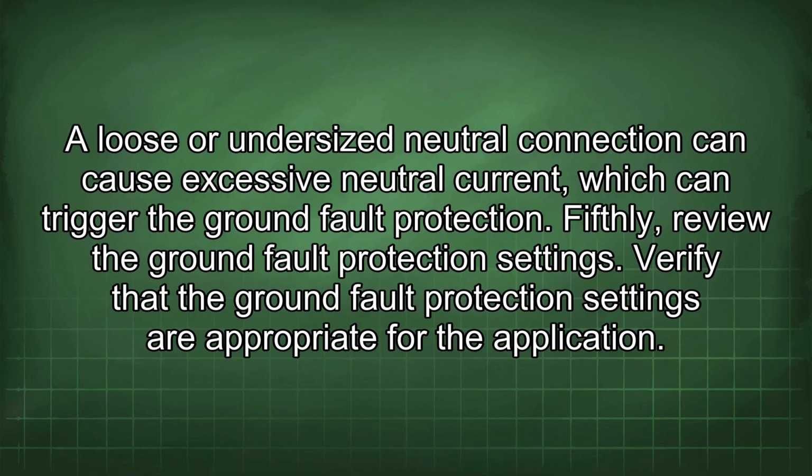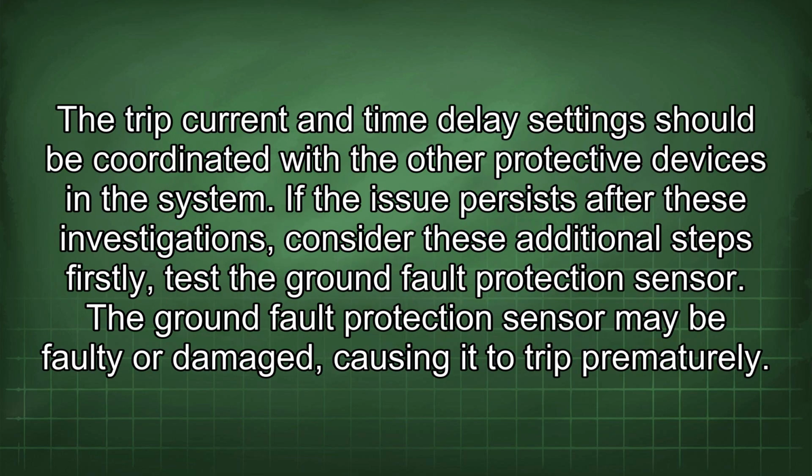Fifthly, review the ground fault protection settings. Verify that the ground fault protection settings are appropriate for the application. The trip current and time delay settings should be coordinated with the other protective devices in the system. If the issue persists after these investigations, consider these additional steps.